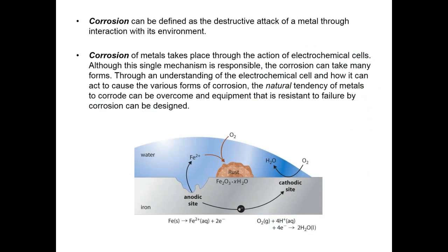What is corrosion? Corrosion essentially is a destructive attack on the metal. Now, it may surprise you that this is actually taking a refined material and going back to its original state. In other words, when we refine steel, we're actually using ore that's derived from the ground. The ore is the lower energy state of the material, so rusting is basically going back to its original form. What happens is that you have an electrochemical environment where one acts as a corrodant or an oxidizing agent and the other is reduced.